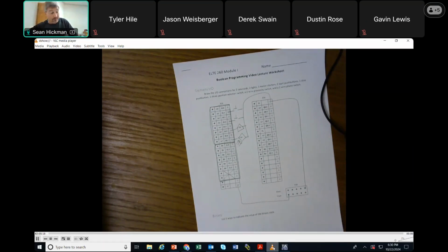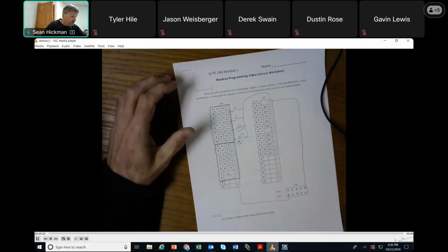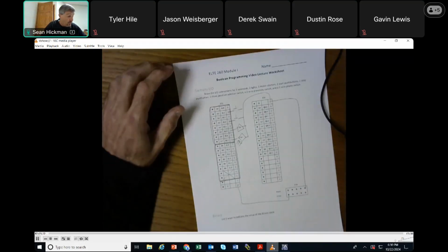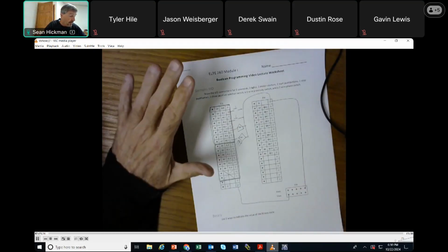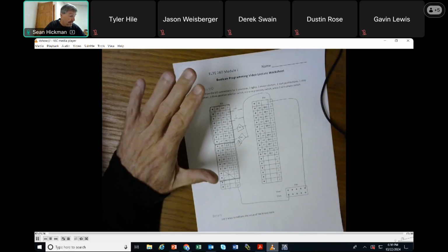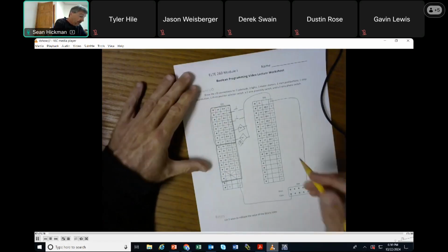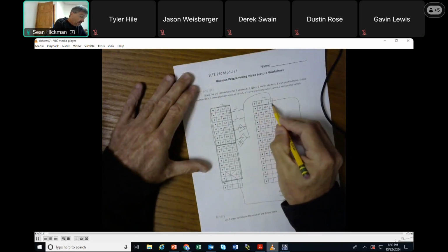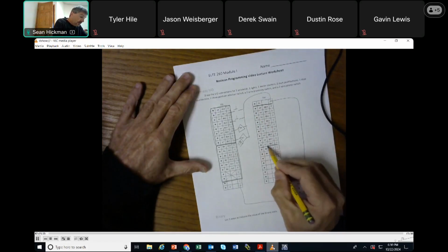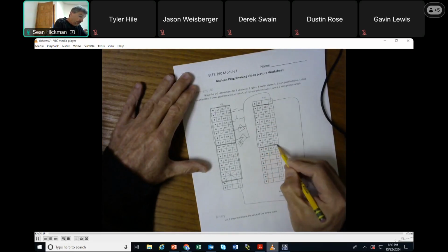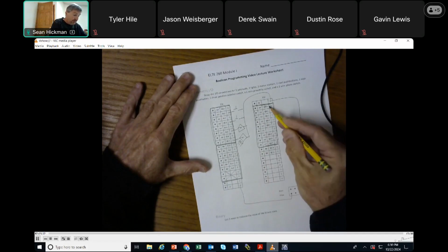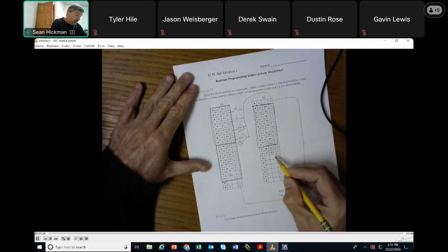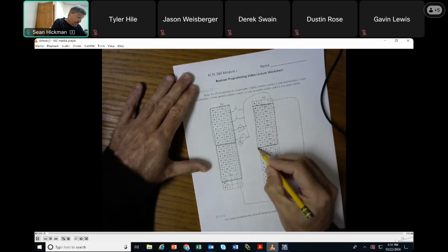The outputs are a little bit weird. Ready? The output is organized by 8s again. So if I look at this, Q7, this is my first byte, 0.0 all the way to 0.7. And then if I had a second one, it'd be 1.0, 1, 2, 3, 4, 5, 6, 7. This would be the second.